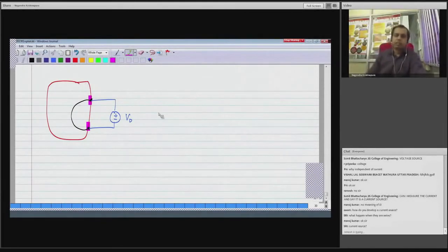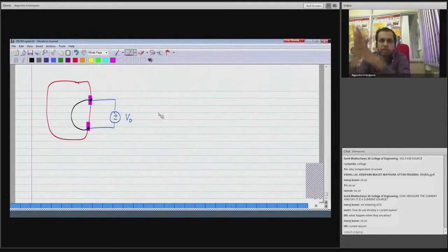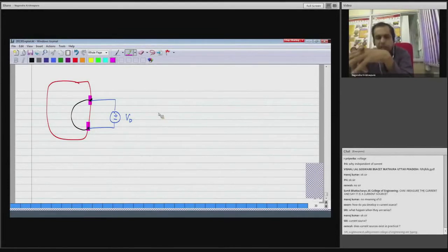In fact, somebody asked this question right at the beginning of the lecture. If you have a voltage source and you apply a short circuit across it, what happens? This is a sub-case of having two voltage sources in parallel with one of the voltage sources being 0, because a 0 volt voltage source is a short circuit. So a short-circuited voltage source is equivalent to two voltage sources in parallel whose values are not equal. That's not possible. So in this case, you cannot find what is inside by applying a voltage source, because that gives you an inconsistent condition.